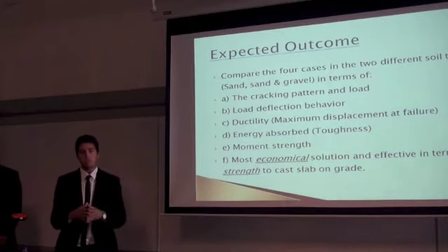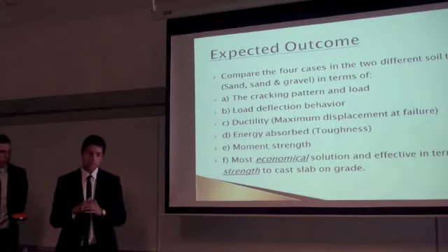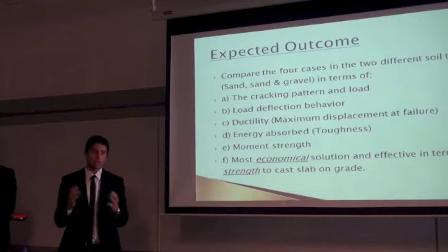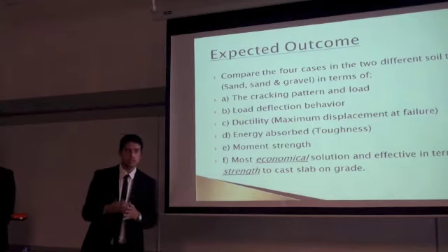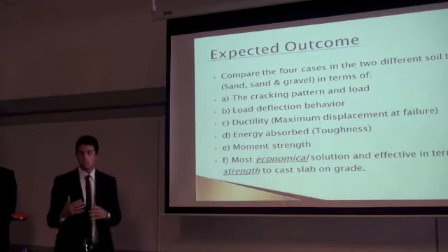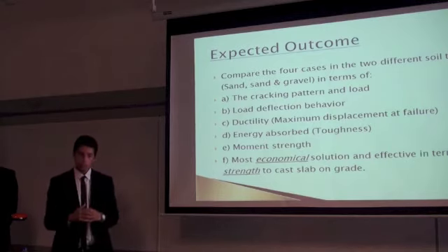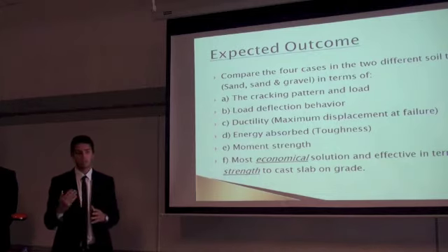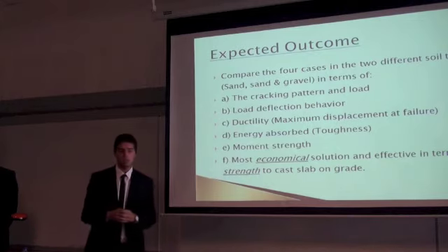As our main aim is to reach a mix where we could not use any type of reinforcement, like in large warehouses, like in the airports. The slab on grade is subjected to very high loads. We want to reach that, instead of using reinforced slab on grade, we can make it fiber reinforced concrete.